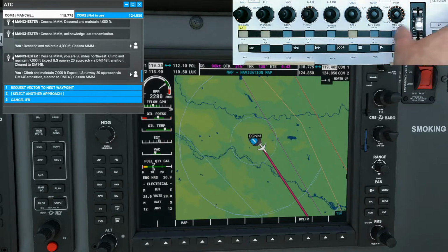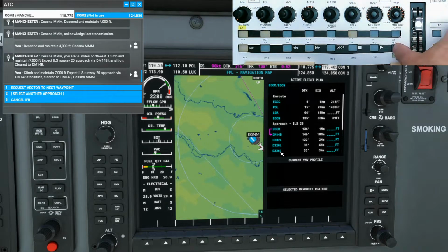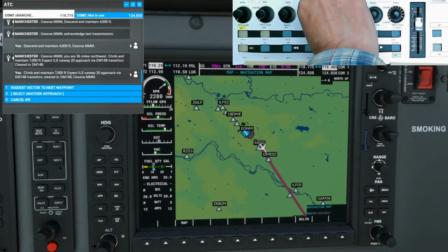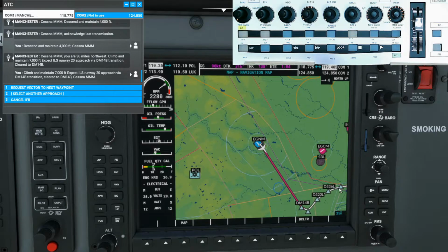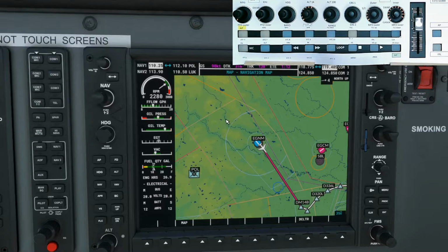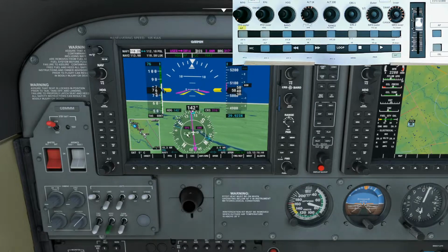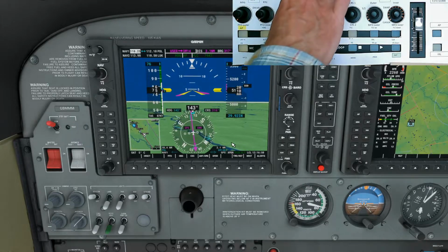And now if we're going to have a look at our flight plan, there it is, and that's all the sequence that it'll be taking us. So we can see that on the map now. Let's get that out, and if we just range a little bit, you can see here's our approach path 14B, and it'll follow that. So let's go back to the primary flight display, and we'll make sure that we are now in GPS. We are, and nav mode.